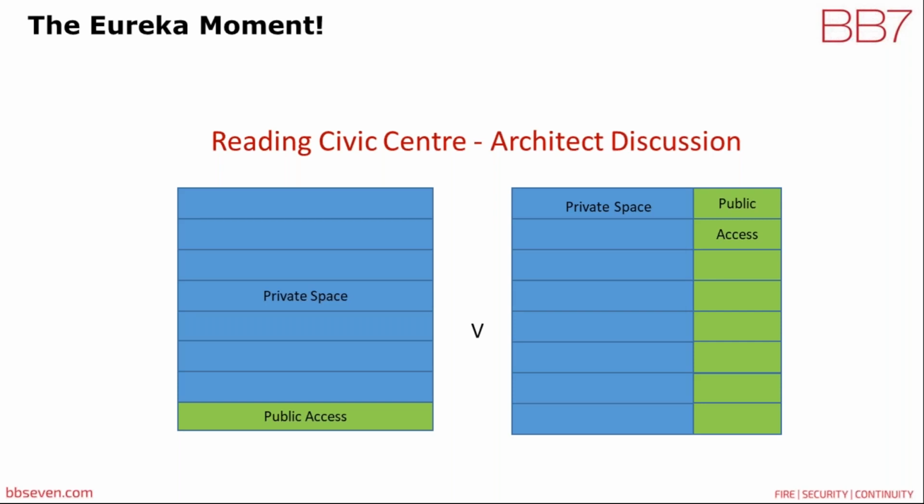So the value of the horizontal zoning was that it ensured that the public remained on the ground floor. However, it also meant that the staff had to continually come down from the upper floors, which was inefficient, but it made access control and the public divide easy. Vertical zoning allowed for direct contact with the public on each floor, made it more efficient for the staff, but it also required customers to have access to every floor. That made zoning more difficult and security more comprehensive.